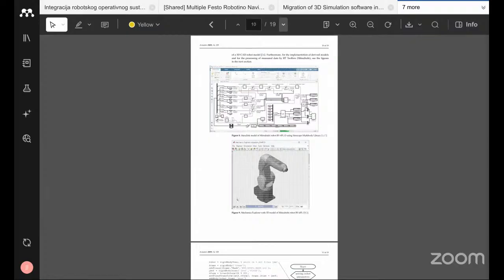So this figure 8 is showing the Simscape Multibody blocks. The robot model is shown in Simscape Multibody: solid, revolute joint, rigid transform, world frame, mechanism configuration, joint actuator, joint sensor, and a solver configuration. Mechanics Explorer will give you the visualization of the 3D simulation.